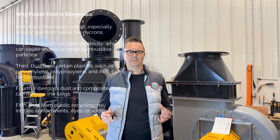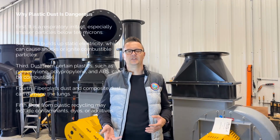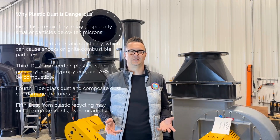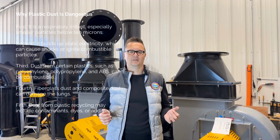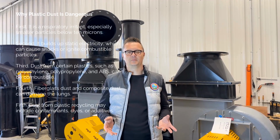Why plastic dust is dangerous? Plastic dust presents several hazards at the same time. First, it is a respiratory irritant, especially smaller particles below 10 microns. Second, it builds up static electricity, which can cause shocks or ignite combustible particles. Third, dust from certain plastics, such as polyethylene, polypropylene, and ABS, can be combustible.